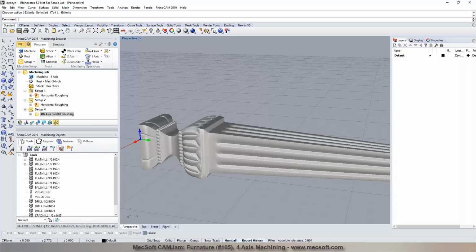And using the drive surface in there would allow then the A rotation to occur, where if you did strictly 3-axis, then it would just. That is correct. The A would be basically locked to a given orientation, and then you would be programming it. Got it.